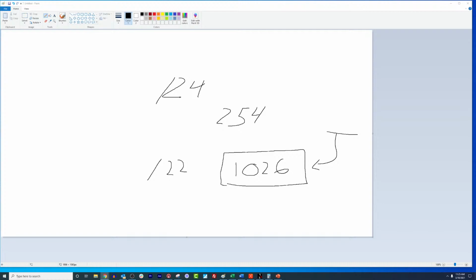Cornell has a good BAS standard that you can copy, and create a naming standard and start applying that to your HVAC systems. By doing that, you're going to make it to where you only have to train people once, and then they can go to the building and everything's going to be named the same. It also makes it much easier to train your tenants if you're using any tenant-facing applications, because all the points are going to be the same.